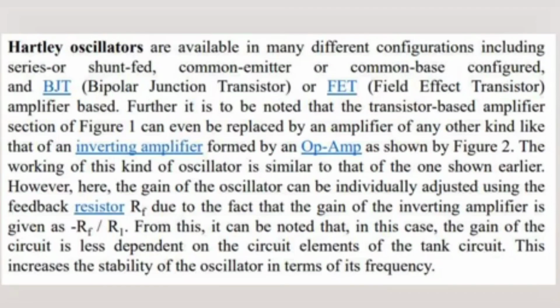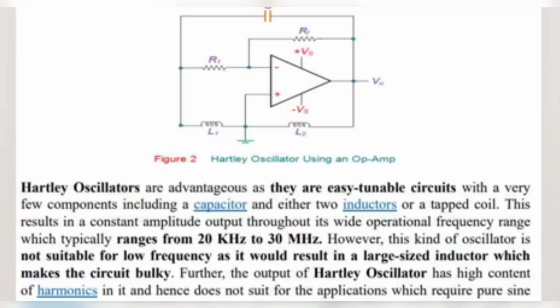This increases the stability of oscillation at the oscillator in terms of its frequency. Hartley oscillator using an op-amp is shown in figure. Hartley oscillators are advantageous as they are easily tunable circuits with very few components, including a capacitor and either two inductors or a tapped coil.